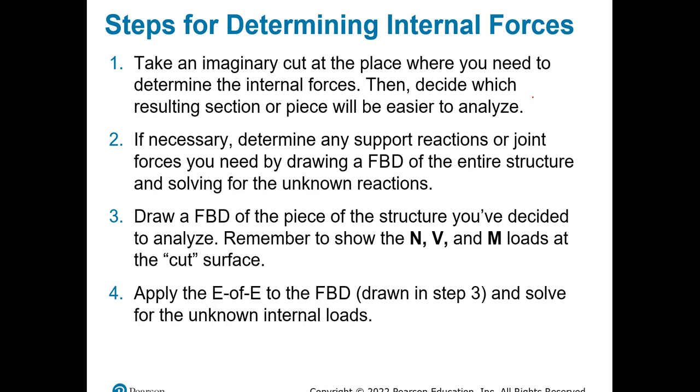So, steps for getting these internal forces. First, we need to take an imaginary cut at the place where you need to determine the internal forces. Then decide which resulting section or piece will be easier to analyze, and that's directly connected to everything that we have taught. You will look at the exercise or the case, see where you have more unknowns, and based on that you will make your decision. If you decide to go with the harder side, then that will be fine too.